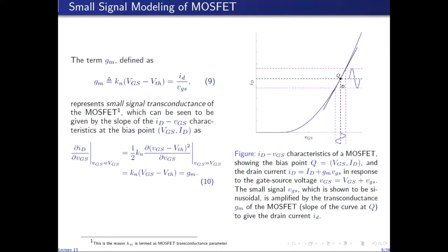So the MOSFET, the NMOS amplifier, then produces the total drain current, which has sinusoidal dependence. So this sinusoidal waveform is GM VGS. This is the small signal drain current. This sinusoidal waveform is the small signal drain current riding over capital ID, which is the DC value.